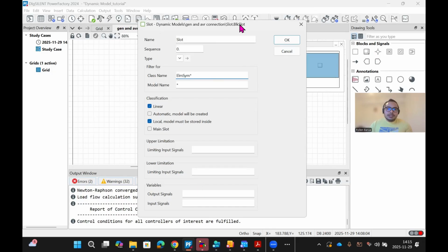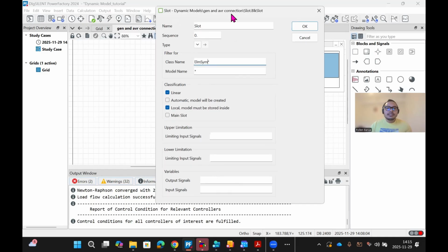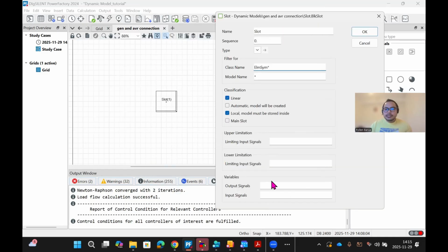And now what we need to do is find some variables. And how do we find the variables? We already discussed. You go to help functions and go to technical reference. That will show you what the parameter name is and what it represents. For example, first let us write, we want to get the terminal voltage output of the generator. So let us write ut.